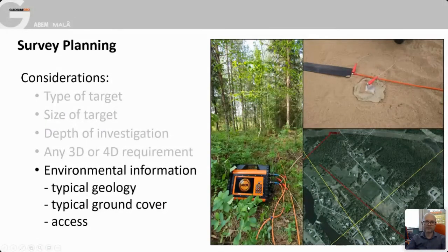Then you've got to talk about ground cover. Well, how easy is it going to be for us to actually take a measurement? If you're working in the commercial world, timescales are very tight. And if you turn up and suddenly find that you're having to work through a forest, or there's a lot of fencing to deal with, then that's going to be a problem for you. So always good to try and get hold of maps, or even better, aerial photos of the site. Try and plan where your survey lines are going to be put in.